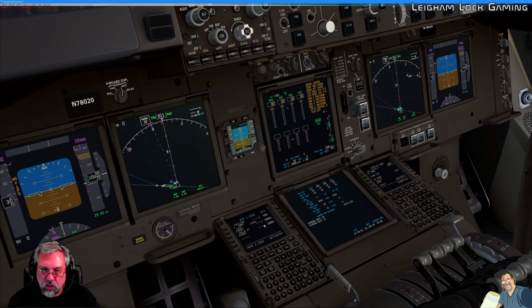So all of this looks good, and if you continue on beyond there, you'll see that this information is just for the go around. So if something happens and we can't land, we'll climb back up to 500 feet on a course heading of 224. We'll then turn left 189 degrees heading towards the Chant waypoint. Go about 18 nautical miles and enter a hold at Chant, and then wait for guidance back down to JFK should we need to perform the go-around procedure. So all of this looks good and is standard, so we can move on at this point.